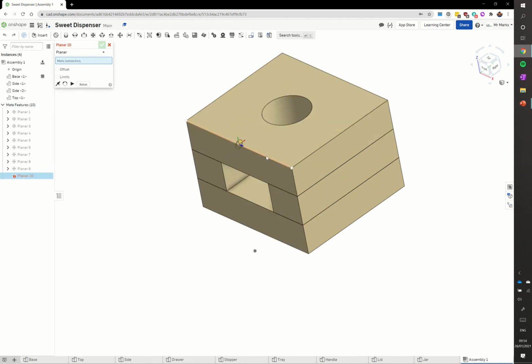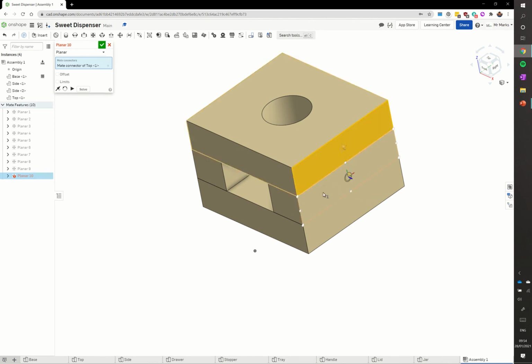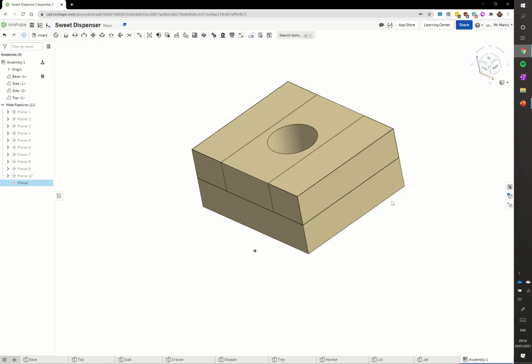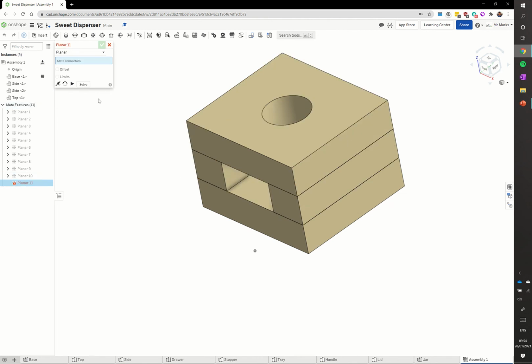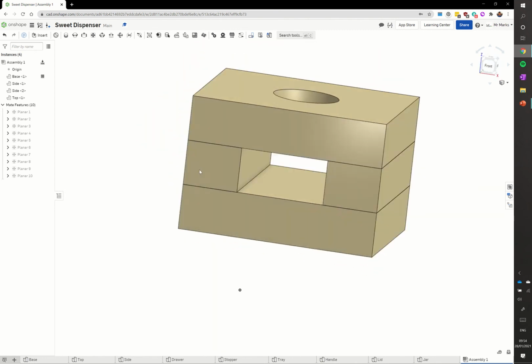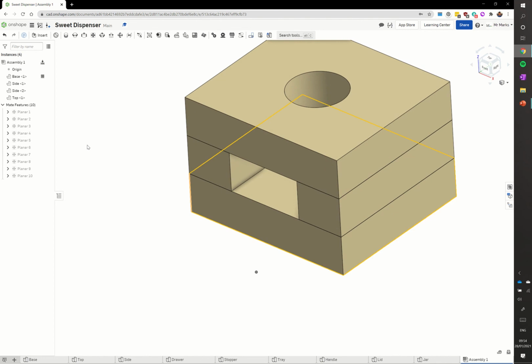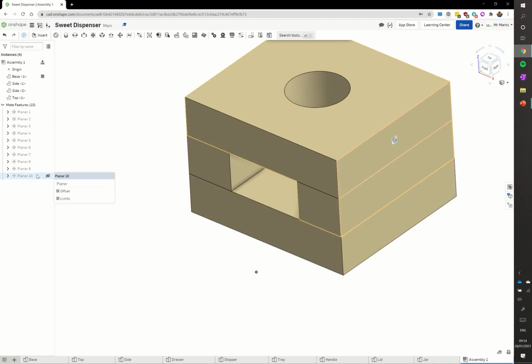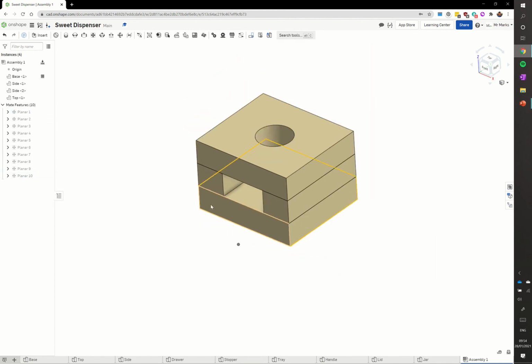And if you ever try to add a constraint when you've already added something, just see if we get an example here. So you'll see, if we close that, it's taken away. It had a wee exclamation mark there. It didn't like that because we'd already had a constraint there. So it was what we call over constrained. You should just be kind of light grey down here. If you've got anything that's orange, something's not quite right.